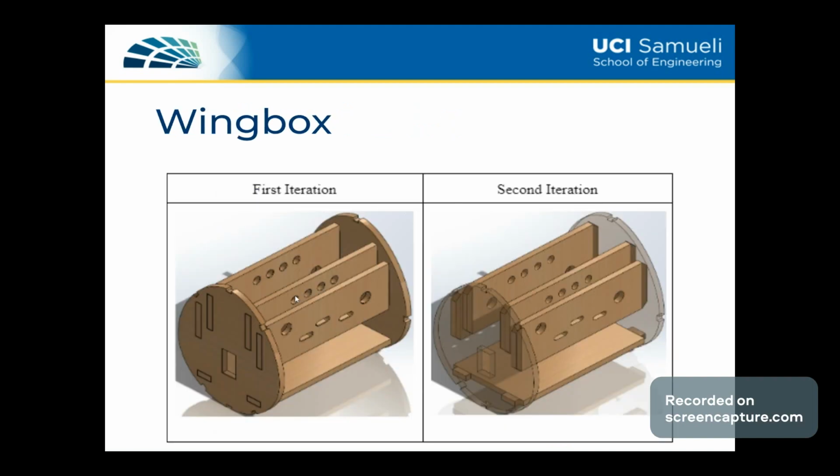In the first iteration, all contact surfaces were chamfered slightly to simulate sanding. In the second iteration, the outer ribs to former attachments were changed from 90 degrees to 45 degrees. For every design iteration, 12 local interactions had to be changed, requiring a lot of manual effort.